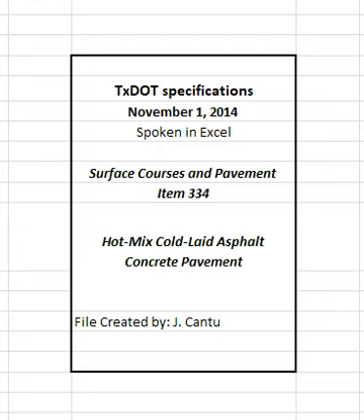If the mixture placement temperature is greater than 175 degrees Fahrenheit, then design, produce, place, and compact the mixture in accordance with the applicable hot mix asphalt specification.